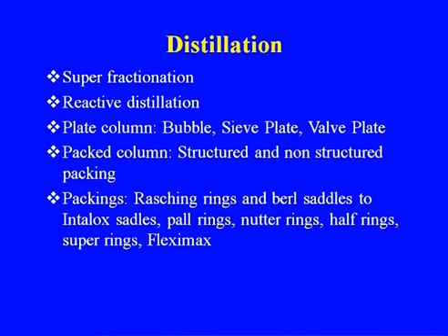So these are some of the developments that have taken place in distillation: superfractionation, reactive distillation, plate columns such as bubble, sieve and valve plates. Then there are packed columns, where again a lot of development has taken place, with structured and non-structured packing. Earlier we normally used Raschig rings and Berl saddles, now it is interlock saddles, Spraypak, Nutter rings, etc.